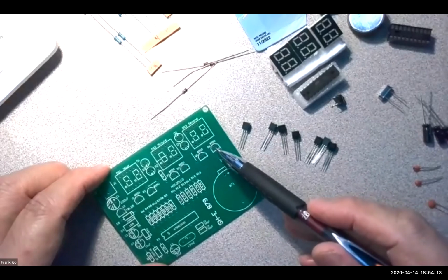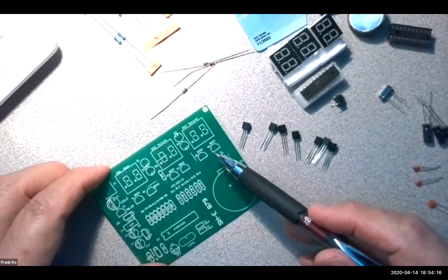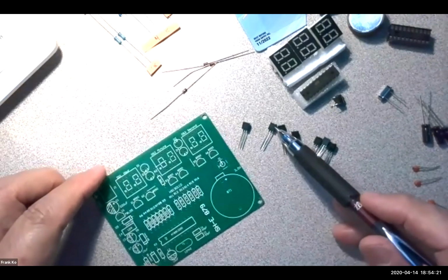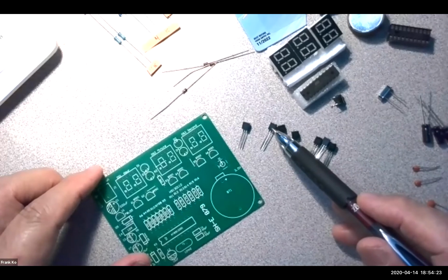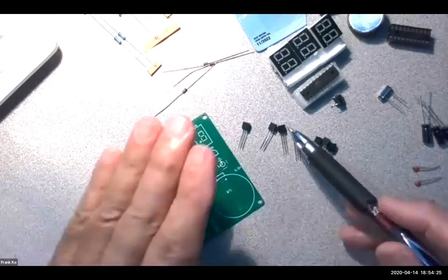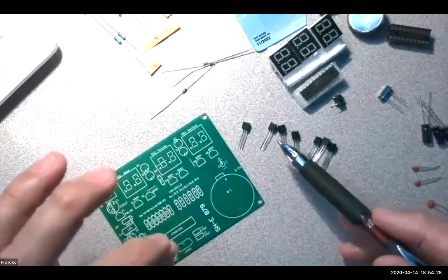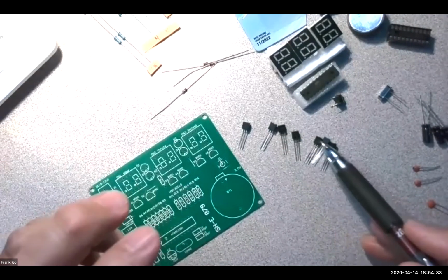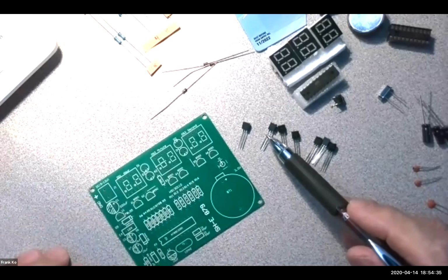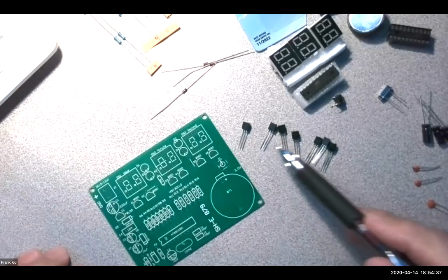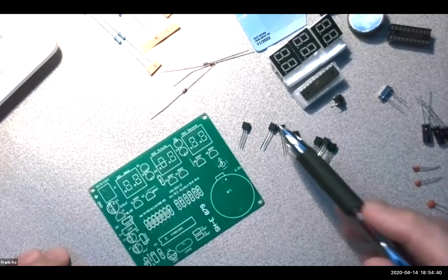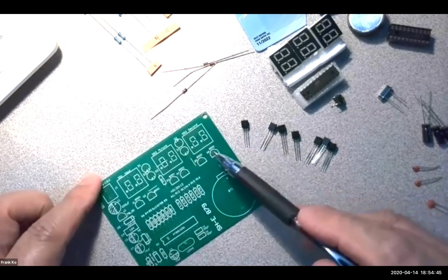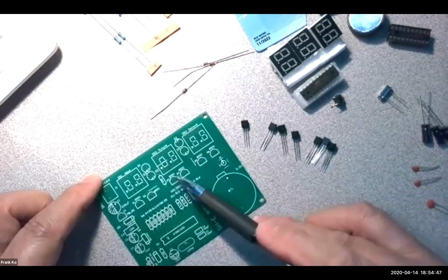These happen to be 8550 transistors, and 6 of these are 8550s. You can tell what they are by looking at the flat spot of the transistor. Hold it up to light at a certain angle, and you'll be able to see the part number very clearly printed on the face of these guys. So these 6 over here on my right happen to be 8550 transistors. This single guy over here does not have that same marking. The single guy here doesn't go in Q1, 2, 3, 4, 5, 6.